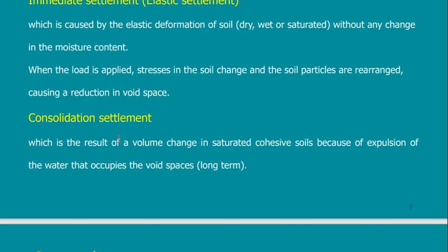Consolidation settlement, as we said, is another approach. It is the change of the amount of the voids also, but not because of this, but because water is expelled outside, because these voids are not full of air, they are full of water. So if you try to compress it, it will not be compressed. Water is not compressible. If you take any volume of water and try to compress it, it will not be compressed.